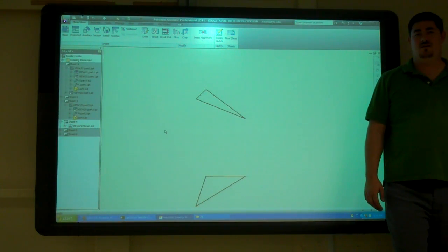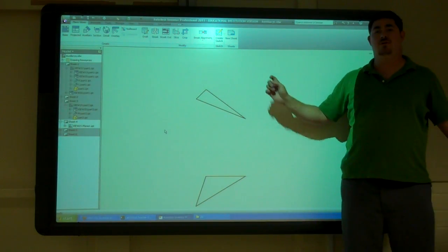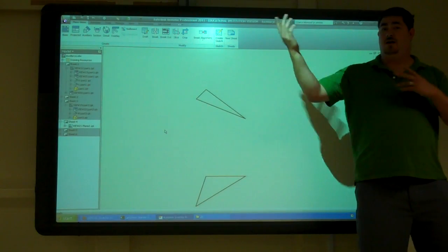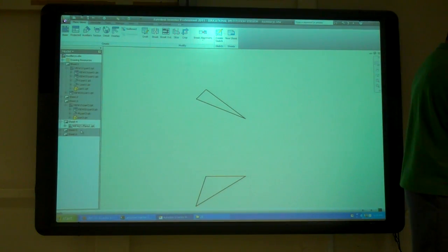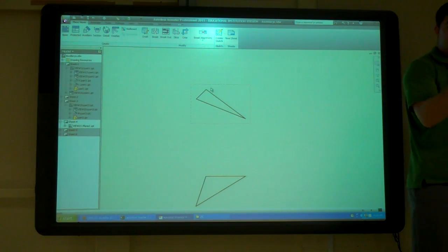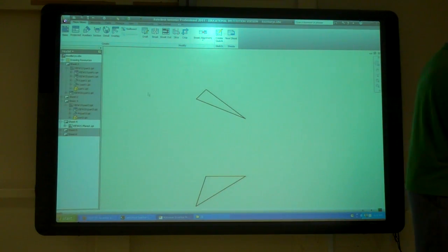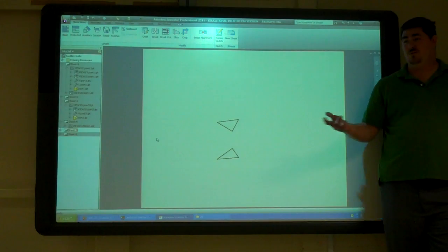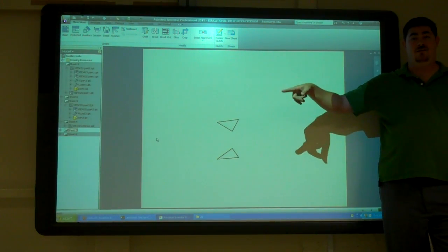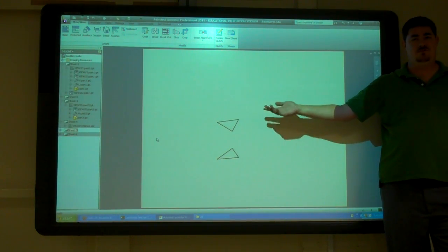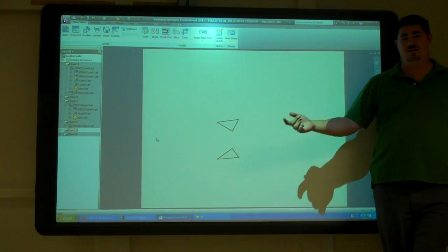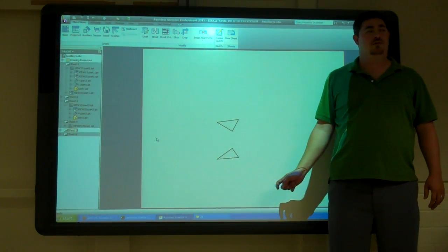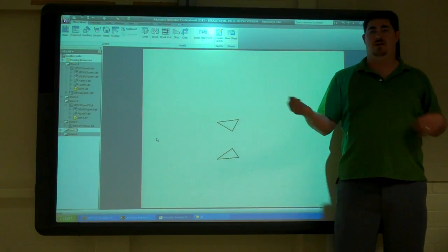This one you want an edge view, or you? Yeah, I want true shape. The true shape. So get to a true shape view. And you could do it from either way. And then going like this here, I've already got one set up so you can do an edge view real easy. But on this one, there's not one. So however you come off of that to get to an edge view, that's fine. But there should only be one step between what you have here and getting your edge view. There should only be one step in between, right?